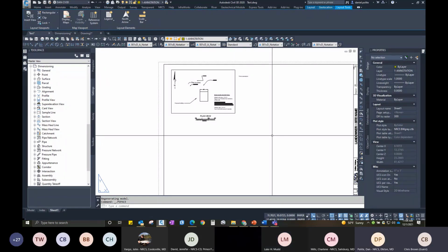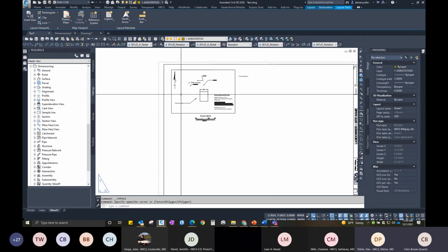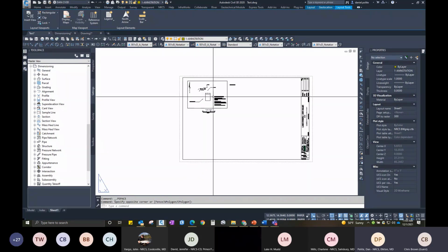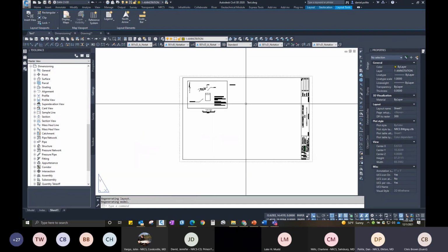So sometimes, and this is across the board, and we'll probably go over this once I create the model space and paper space training, a lot of times, like when you have a large design going on and you have multiple viewports and you create different viewport scales, sometimes you have to come in and out of that page or that sheet and come back in, and then it'll show up. It's just something with Civil 3D that you have to do, and it does take some time sometimes. So what's happening with you is normal.